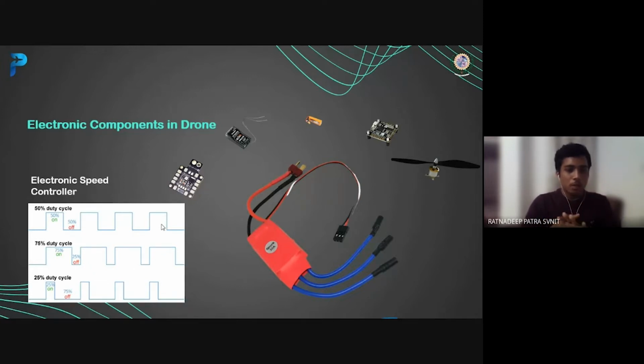As seen in this figure, the first signal is on for 50% of the time and off for 50% of the time. That's why we say this signal has a duty cycle of 50%. Similarly, the second signal has 75% duty cycle and 25% duty cycle. It's just an example. Using these PWM signals, we are basically controlling the RPM of the BLDC motor.